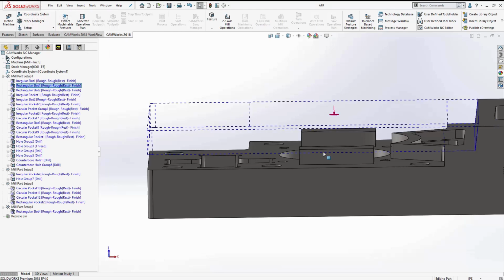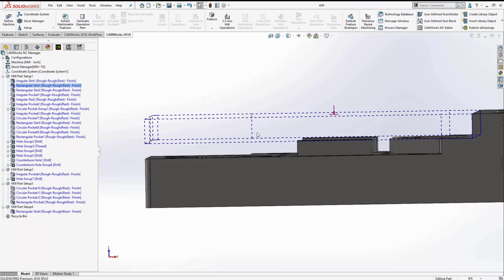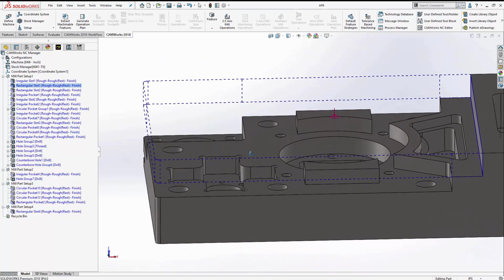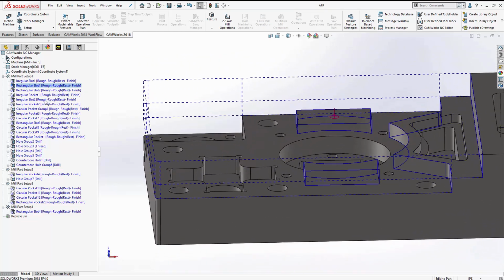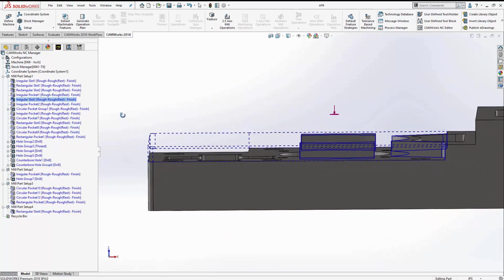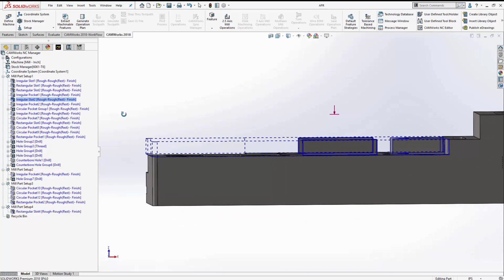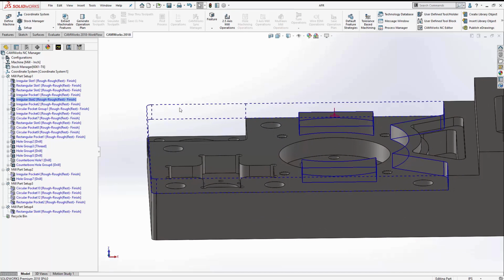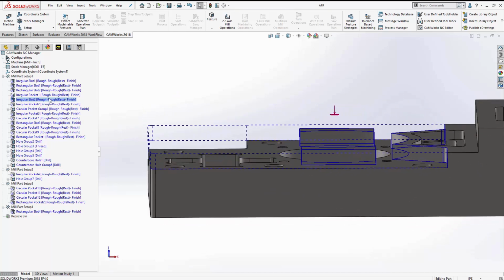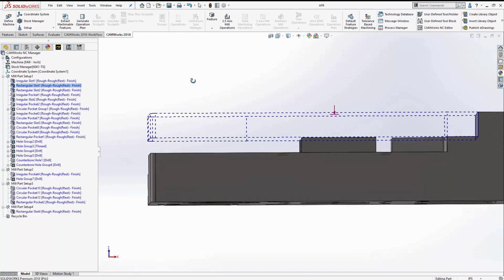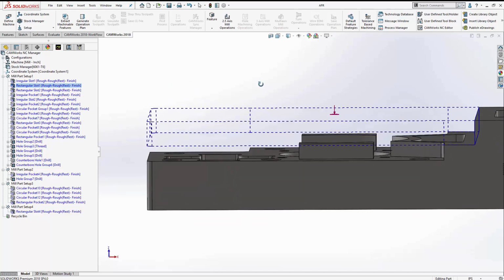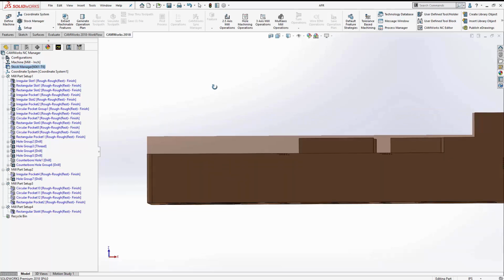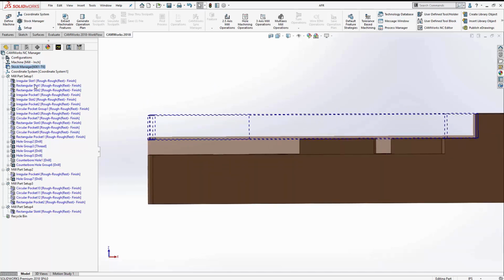Okay, it's now going to generate a rectangular slot at this height and another irregular slot at this bottom depth. So really, with it recognizing features by depth, it gave us just this one depth. It's not going to be cutting a lot of extra air, which this one would be. This would be cutting a lot of air where there's no stock, as you can see where my stock's set up. So you can see clearly that this wouldn't be the ideal option for us.